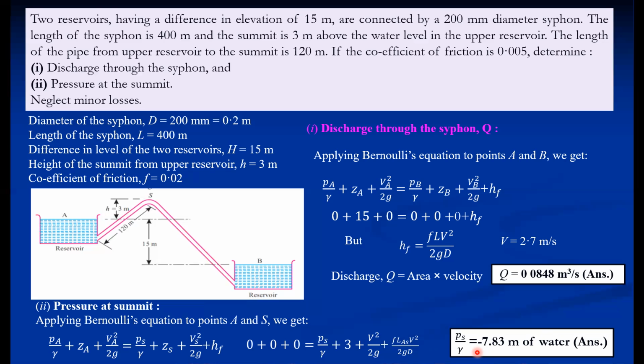That means there is a possibility of flow obstruction. Maybe the flow is partially obstructed, not fully, but because of the dissolved gases. So practically this is not recommended. If this kind of pressure is there, then we have to reduce this height so that the pressure here does not fall below minus 7.6 meter of water. Otherwise 10 minus that is again less than 2.7 meter of water, which is not recommended. Actually, that's why you can think about it practically in this way.